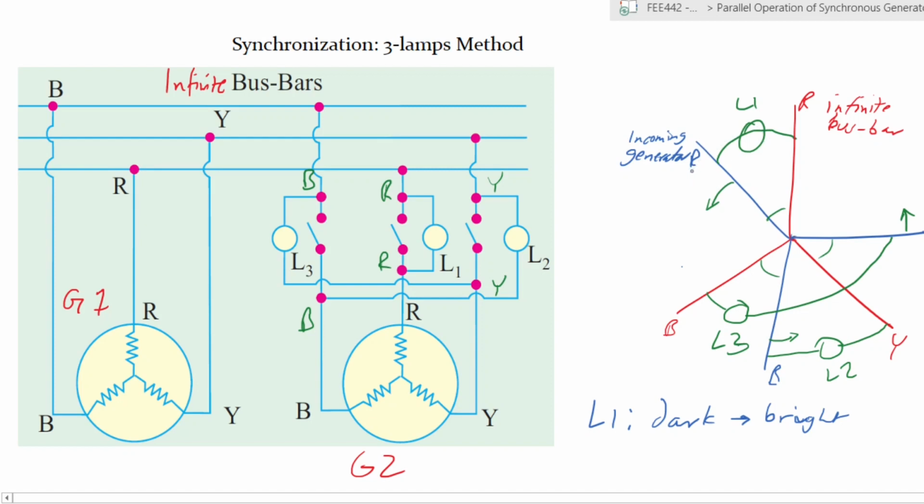So the difference in voltages between the two is increasing, meaning the lamp is getting brighter. The lamp indicates visually the potential difference between the 2 points where it is connected. In the case of lamp 2, it is getting dimmer from maximum. Initially it is far away from the yellow, but because the incomer is moving towards it, it appears to be reducing the potential difference between the two.